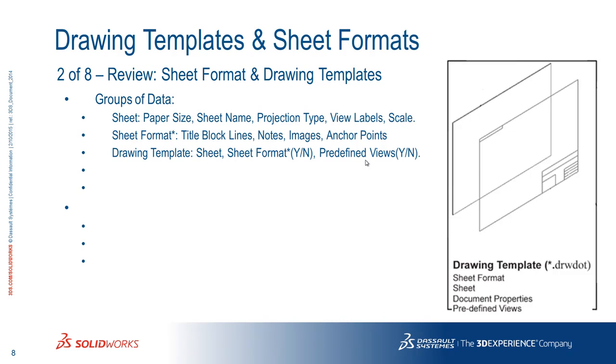And they may contain predefined views. That's what you would use to set up the template so that when you make the drawing from the part, it creates the views for you. The one drawback with predefined views is you will be forced to use the front view of the model as the front view on your drawing, the top view of the model. So if you start out your models poorly for the drawing environment, we will automate the drawing to be poorly laid out. So garbage in, garbage out. It does require a little bit more forward thinking maybe.